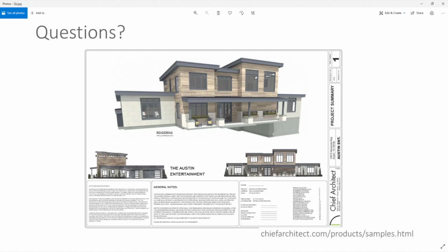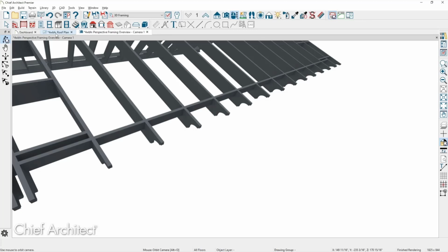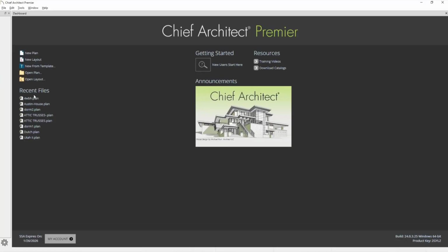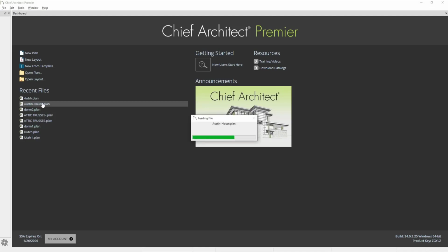So that works like 9 times out of 10, except when I have a cathedral ceiling. When I have a cathedral ceiling, it'll still show the siding underneath the interior portion of the ceiling. And if this isn't a question for today, I'm just letting you know, I do it when I auto build the roof, so that way I know my roof is snapping on correctly on the interior portion. Am I making sense?